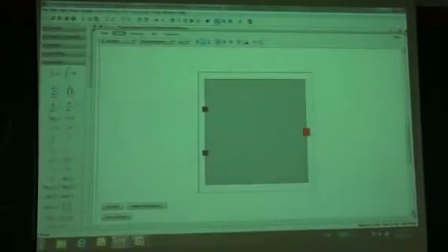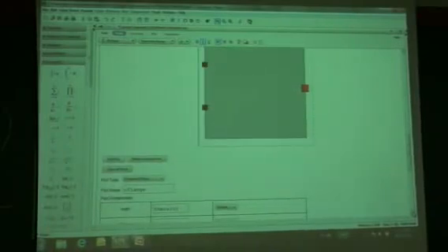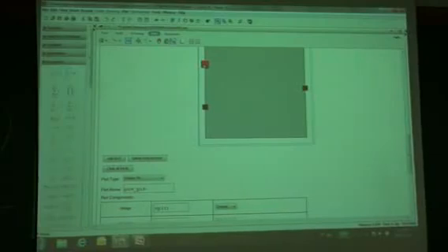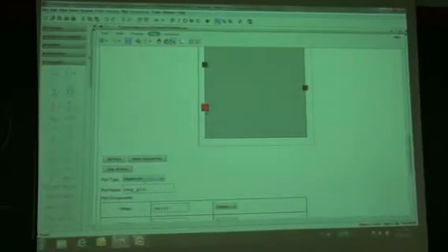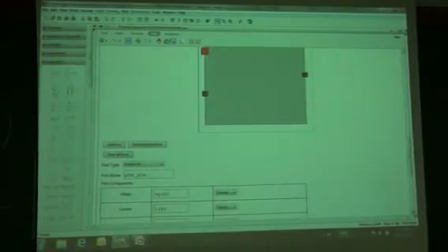This is the stage where you can define how this component is going to look in MapleSim. These are what we call acausal ports. These are the ports that define the interface between this component and other components that you want to connect together. These two ports are actually electrical pins. This is the negative pin, this is the positive pin. And on each of those pins you have certain properties that come from those equations.